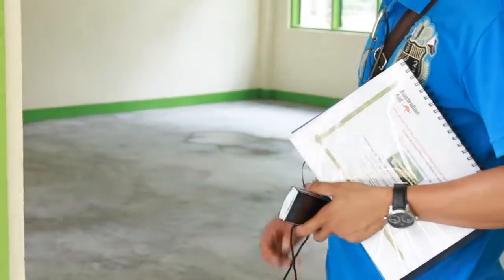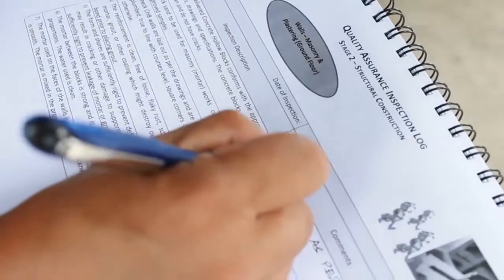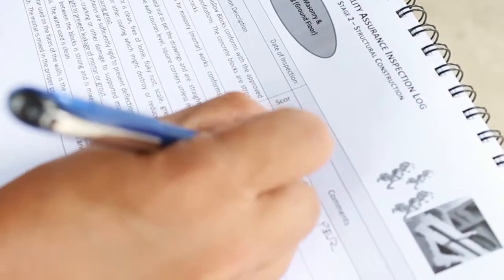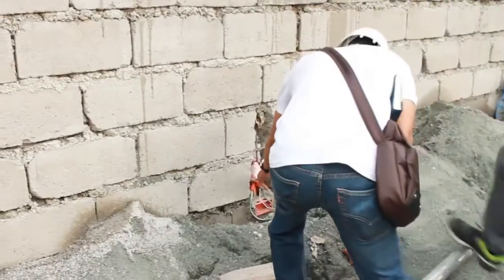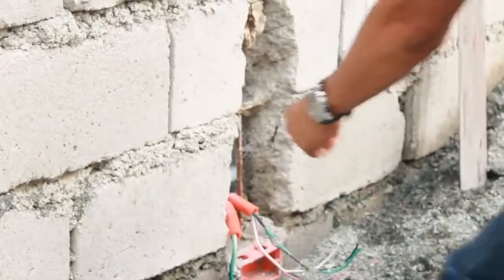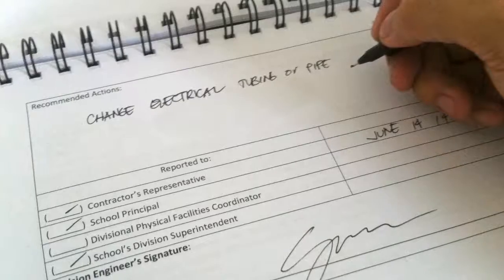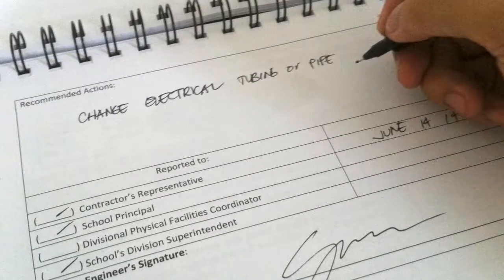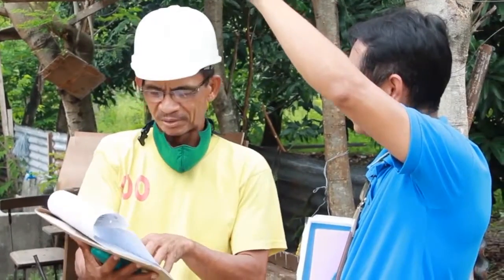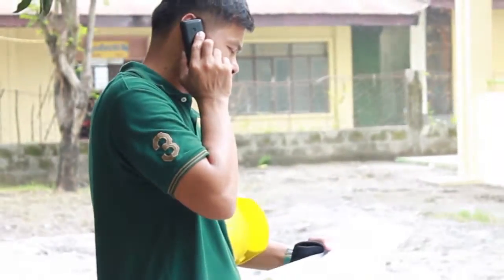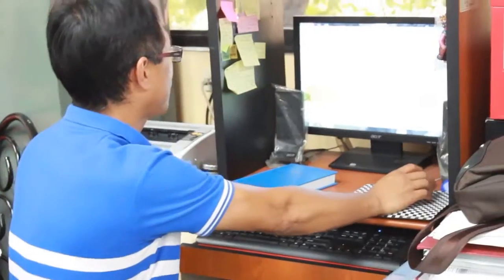The engineer should take the inspection logbook to the site at every visit, and when on the site, should input or record his or her observations on the ongoing construction activities. If during the inspection, the engineer has noted and recorded in the QA logbook any item that requires urgent attention, he or she must inform the contractor of items which are not of satisfactory standard. The engineer must also inform the physical facilities coordinator and the school division superintendent immediately by phone or by email